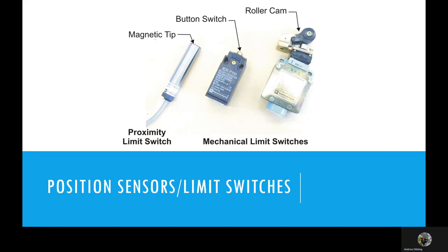Now, again, as mentioned, you do have some cushioning there for your cylinders when they reach the end of stroke. Another way of doing this, particularly in a bidirectional cylinder or in some kind of a sequential operation, is to use some kind of limit switches, be they mechanically or electrically operated.